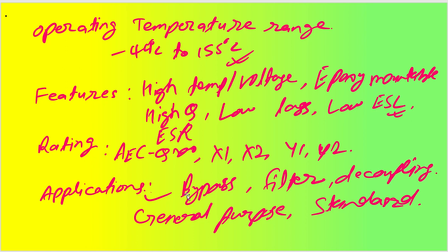If it is mentioned already that these are the applications it can be used for, it can be used in automotive or military grade or space grade, or even medical, or different applications. So if it is written, then it is much better. If it is not written and you are using some consumer application or industrial application, then you can always go ahead with standard capacitors or general purpose capacitors. So this is the understanding of application related to the capacitor selection, okay.